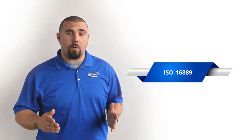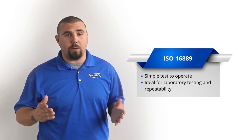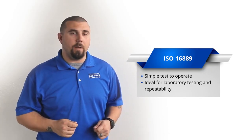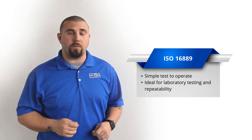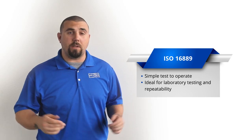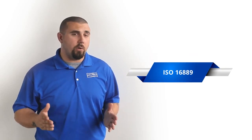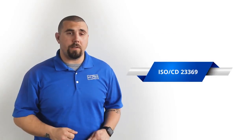Some important things to know about ISO 16889. It is the simplest test to operate and is ideal for laboratory testing and repeatability. Because of this, the test is the furthest from being a real-world example of how most hydraulic and lubrication filters interact with contamination. Also, due to its steady flow rate, the test offers no view on how flow rate fluctuation can impact filter performance. The next test we will be discussing is ISO CD 23369.